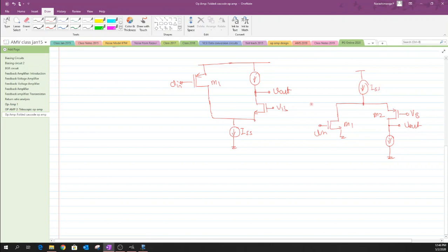So we have analyzed all these circuit setups in the earlier classes. The only thing right now that I am going to do is that I just want you to recall how this change in the configuration of M1 and M2 has really made this VB change. In this case, one could use a value of VB which is only constrained by the drain of M2, so you cannot have a value of VB more than the drain potential of M2.